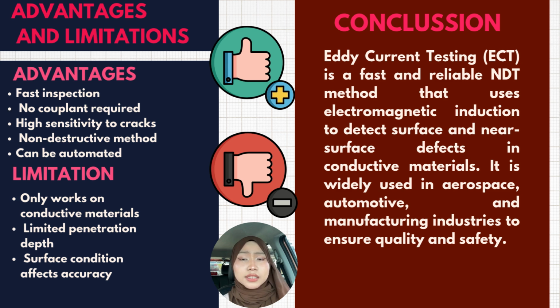However, there are some limitations. Eddy current testing only works on conductive materials, has limited penetration depth, and the condition of the surface can affect the accuracy of the results.